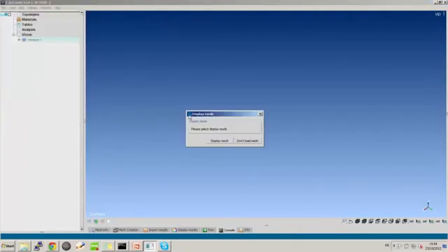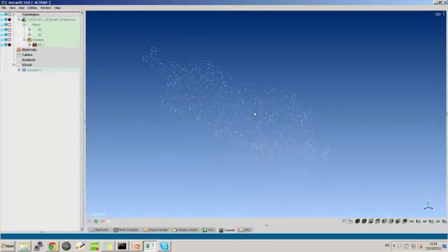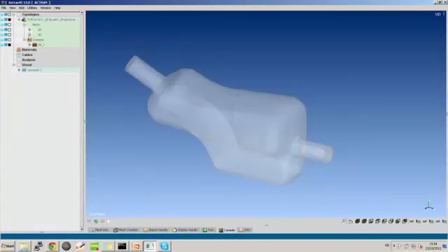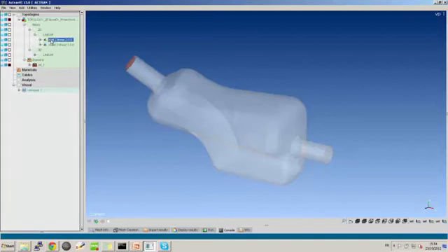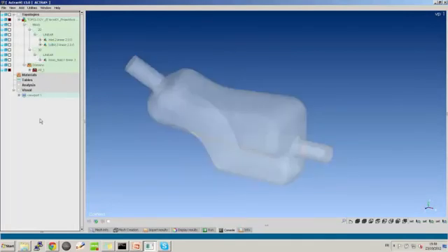In order to start, the first thing I will do is import the first mesh that I have presented. So I am importing this mesh, and we can see that this is a part of an exhaust system. It is actually a muffler, and I have, as indicated, two surfaces for supporting the modal duct components and the interior acoustics. So what we will do at first is, from scratch, start a new Actran analysis.